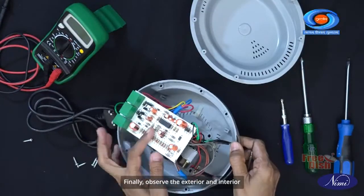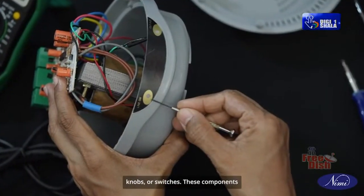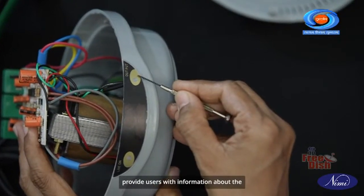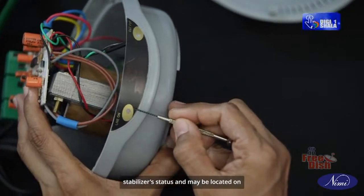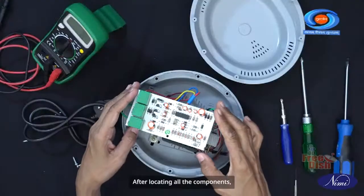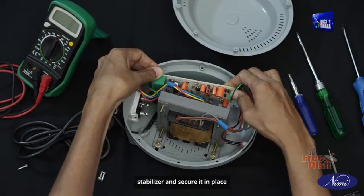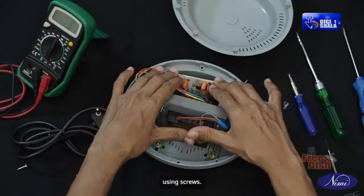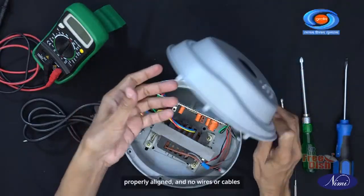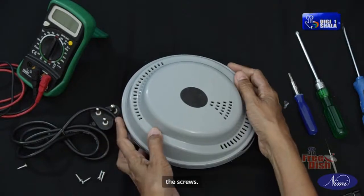Finally, observe the exterior and interior of the stabilizer for indicator lights, knobs, or switches. These components provide users with information about the stabilizer's status and may be located on the front panel or integrated into the PCB. After locating all the components, carefully replace the top cover of the stabilizer and secure it in place using screws. Ensure that all components are properly aligned and no wires or cables are pinched before tightening the screws.